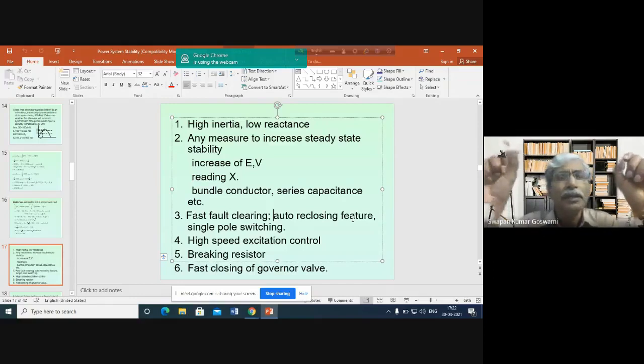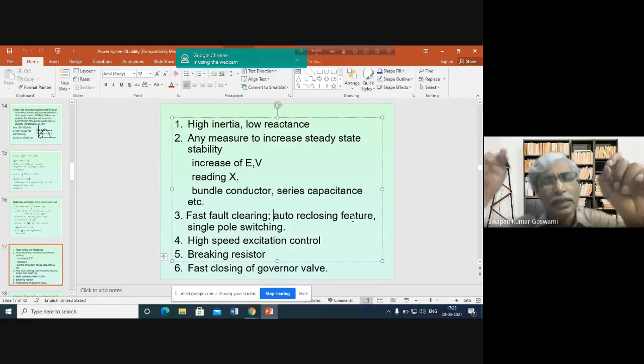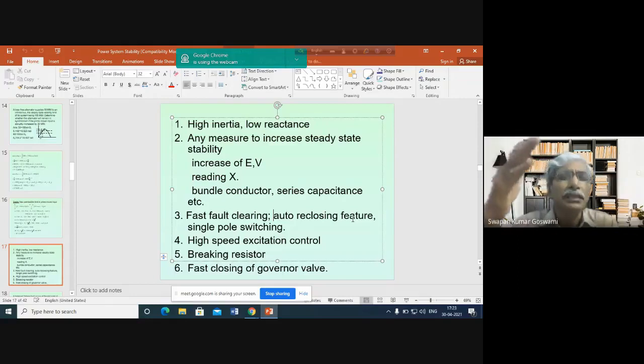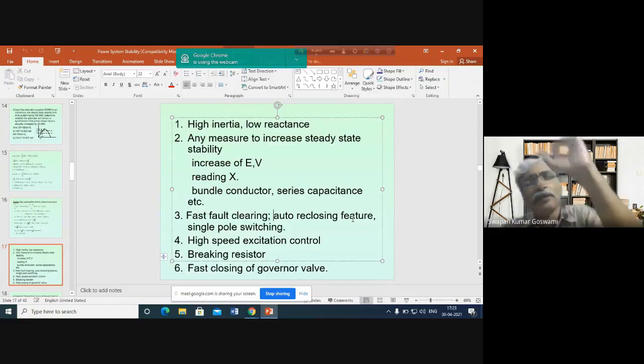That means after the occurrence of the fault, it will open the terminal of the conductor, wait for a short while, and then again close the conductor. If the arc is removed by this time, that means if the arc path regains dielectric strength by this time, then after the circuit breaker recloses, the healthy operation of the system will be possible, and this will help in maintaining the stability of the power system because now again the power flow path is re-established.